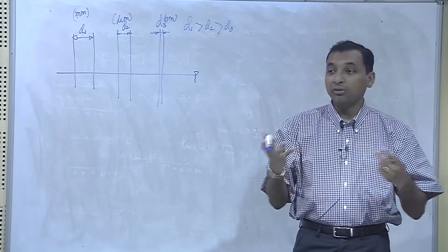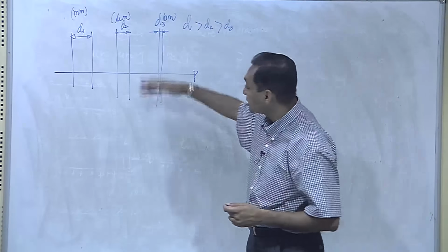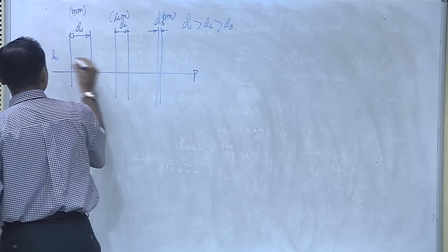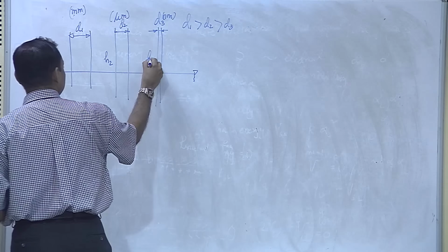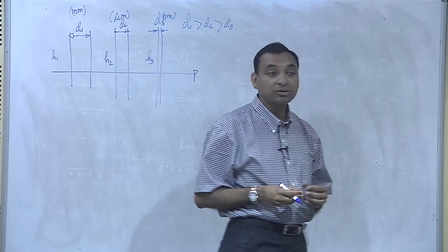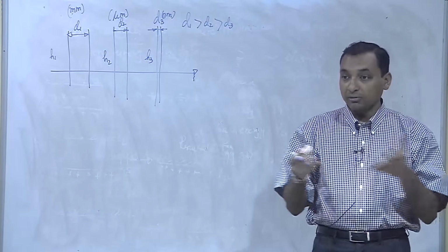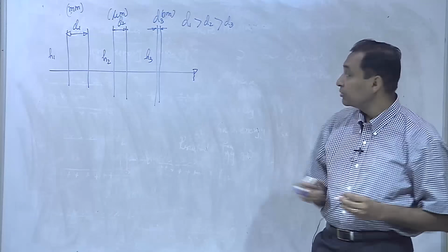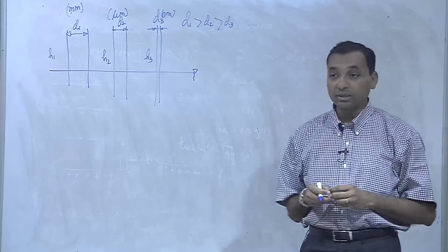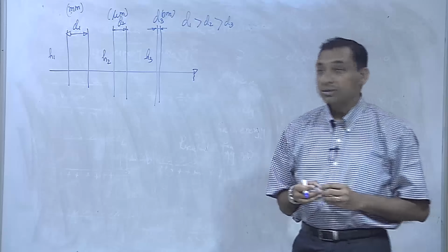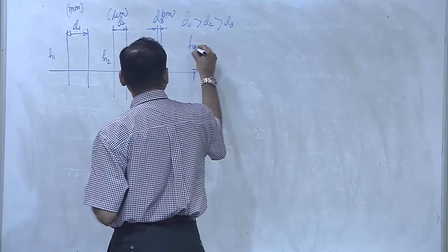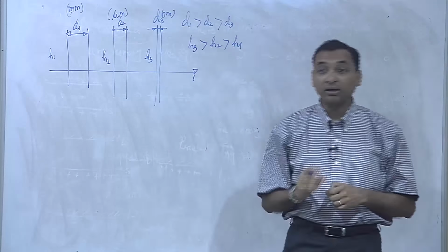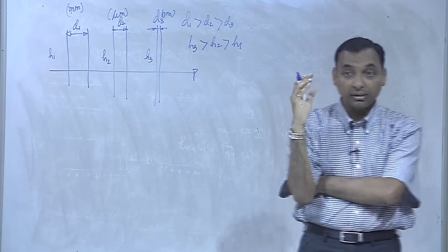So, how do you see any fluid in this case, which one will rise, right. Say this rise will be H1, H2, H3, because it will only rise due to the capillary forces, right. So, capillary will try to raise the liquid. So, will H1, H2, H3 be the same or different? So, H3 will be greater than H2 will be greater than H1. So, the thinnest one will have the highest rise of the capillary. Okay. Why is it happening?